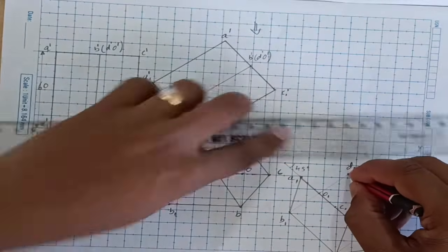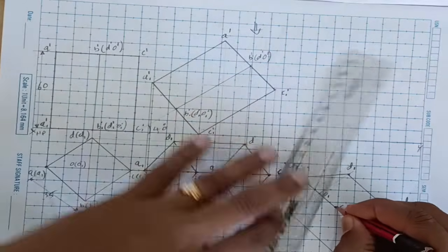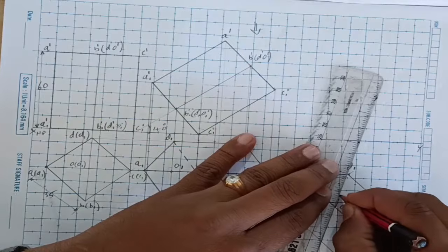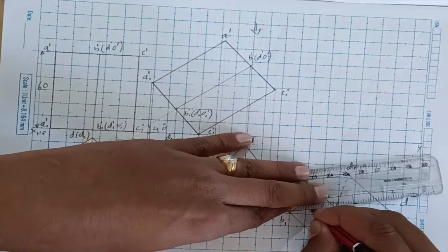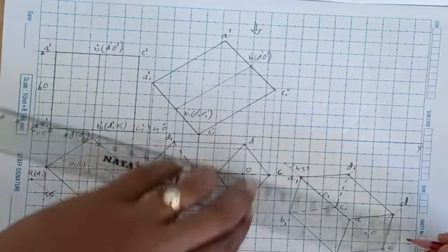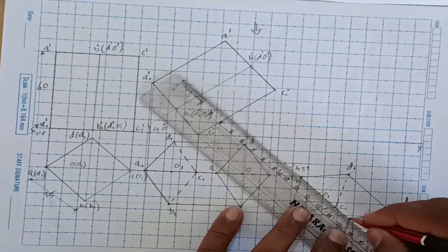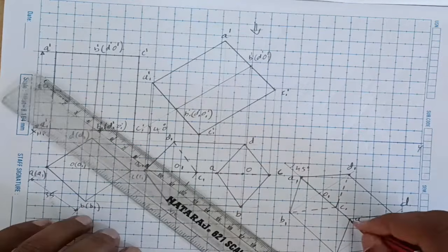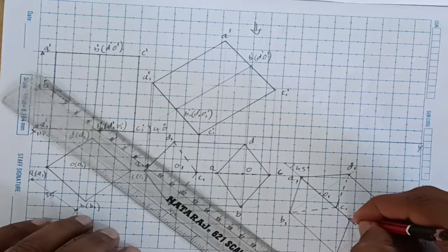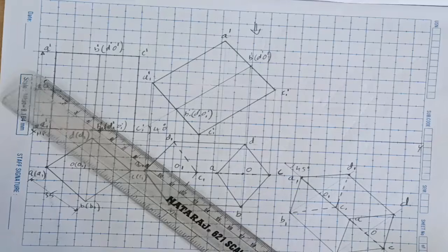And next, we need to draw the hidden edges, that is from C1 to D1, and then C1 to B1, and then C1 to C. When drawing C1 to C, this is visible and overlapping, so we need to draw a hidden line. From the A we need to draw a hidden line, not from the C, because overlapping is there. Then the center line is overlapping, no need to show. One more time, the central axis line need not be shown.